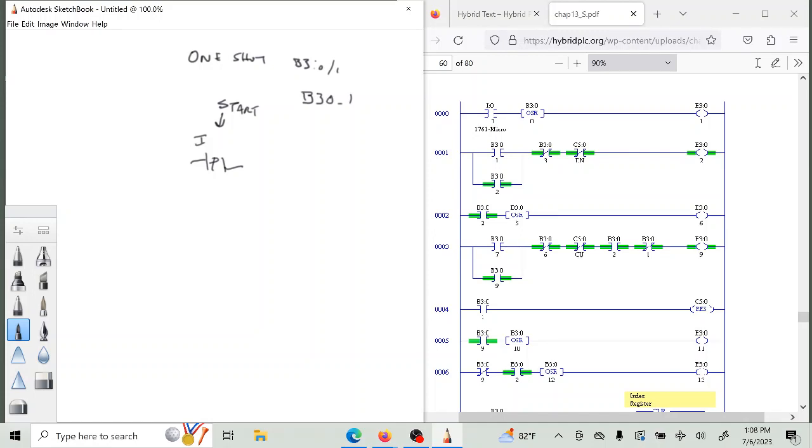But now I'm working on rung 1, not rung 0, and then I have these 2 normally closed that we don't really know what they are yet, but let's just call this coil B3:0_2, and then we would use that B3:0_2 down here. Now, what does B3:0_2 mean? Well, it really is the run bit. So we're running the game.